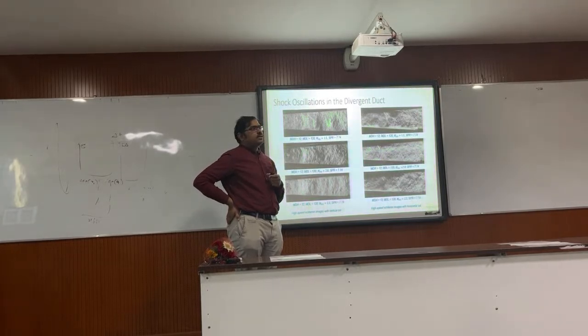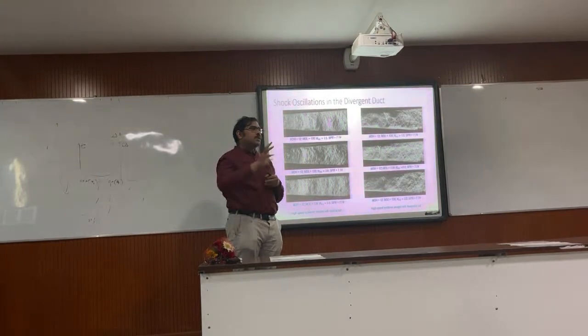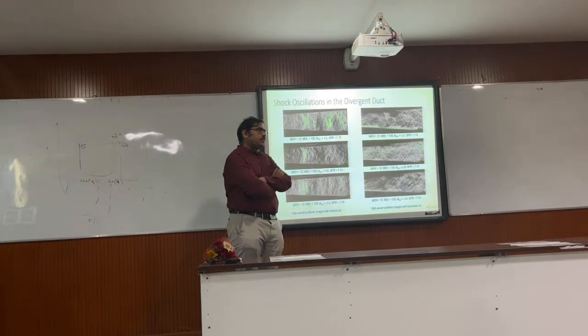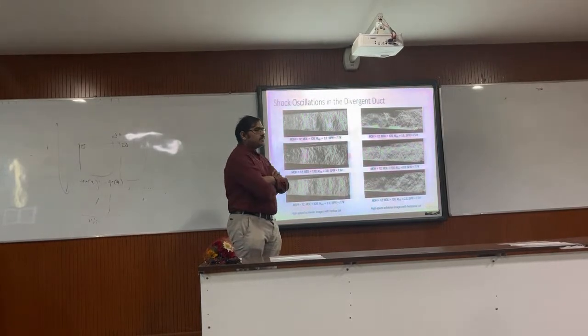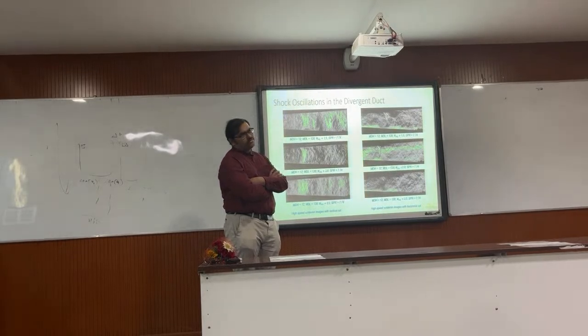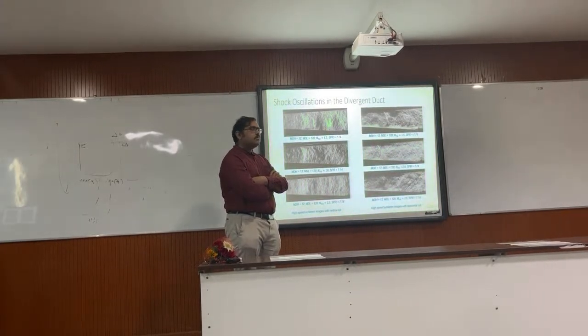The gamma effect comes when the temperature becomes so high that it leads to dissociation and so on. That is really high enthalpy effects, which kick in at very high enthalpy. The enthalpies that we have tested here are not extremely high. They are at medium to low enthalpy, so we won't see much gamma effect. So we can translate the laboratory findings to the intake design.